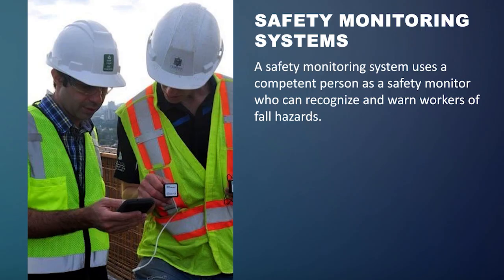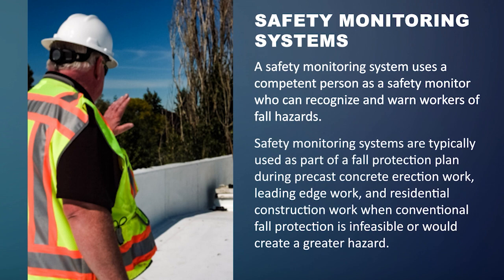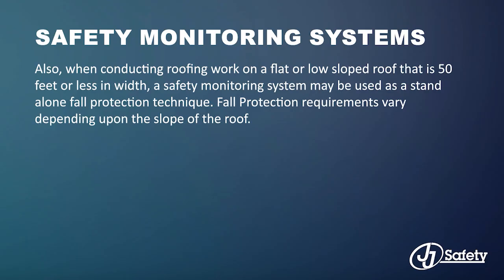A safety monitoring system uses a competent person as a safety monitor who can recognize and warn workers of fall hazards. Safety monitoring systems are typically used as part of a fall protection plan during precast concrete work, leading edge work, and residential construction work when conventional fall protection is infeasible or would create a greater hazard. Additionally, when conducting roofing work on a flat or low-sloped roof that is 50 feet or less in width, a safety monitoring system must be used as a standalone fall protection technique.